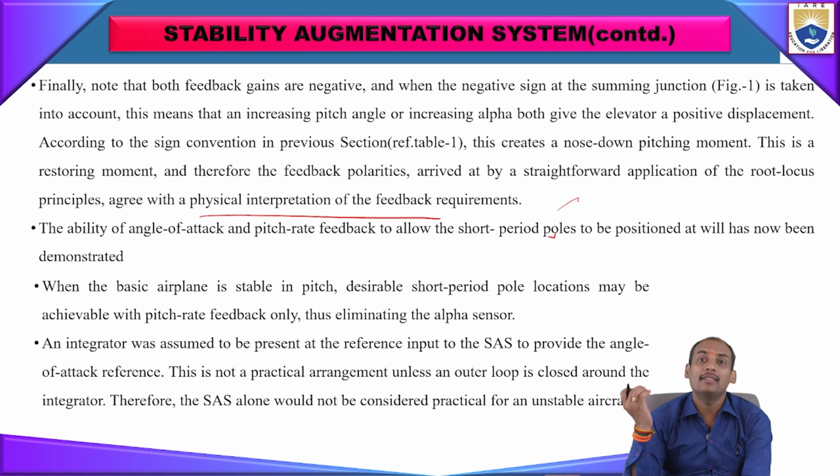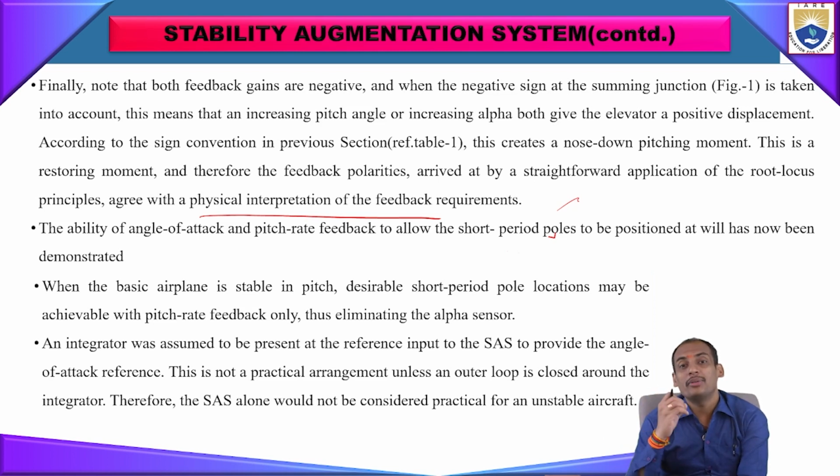Like that here also, for every aircraft, whether it is a passenger aircraft or a jet aircraft, only installing this SAS system will not give you total control of the aircraft. There will be a controlling agent for this also. Sometimes we need to skip the values coming out from the SAS.